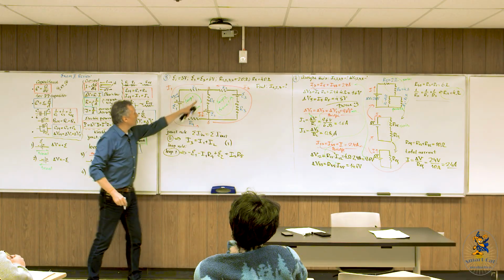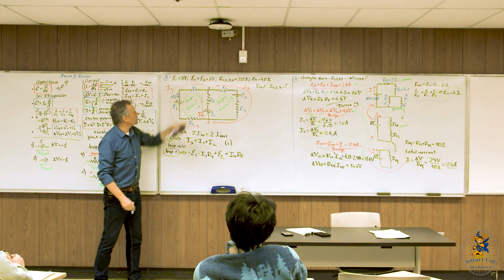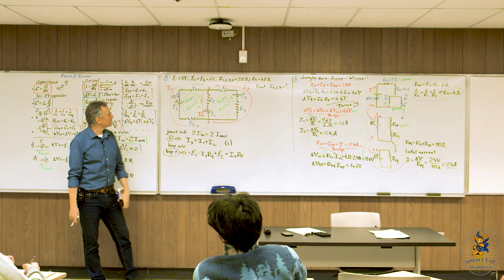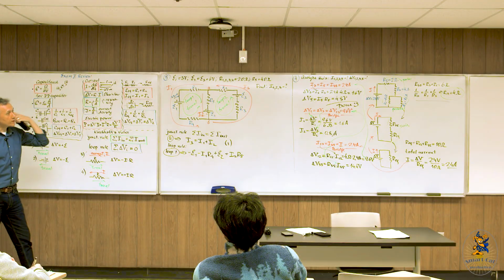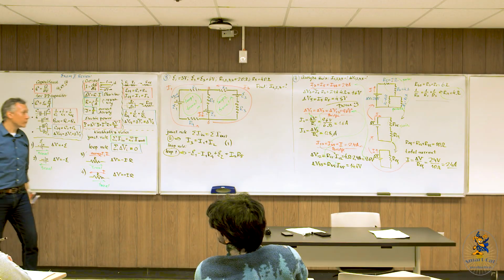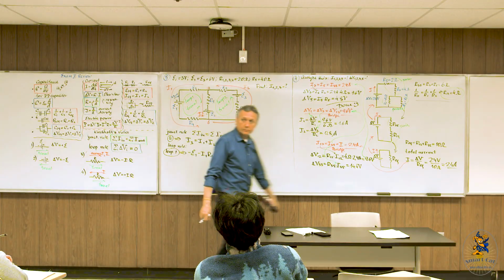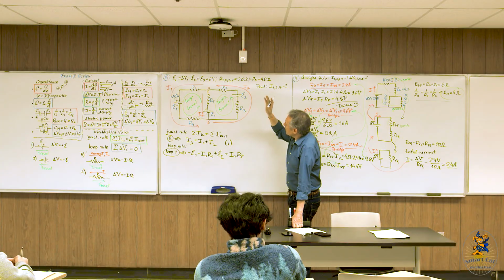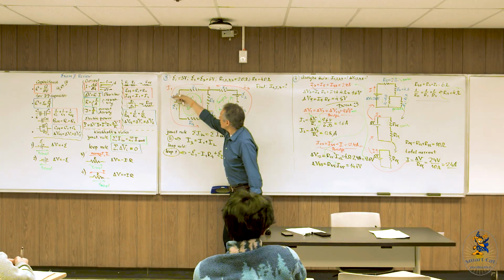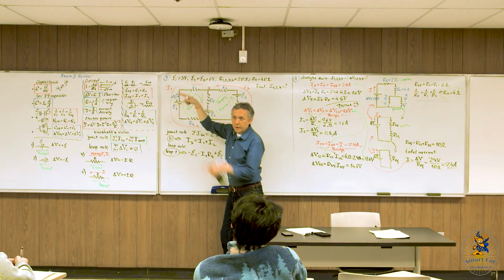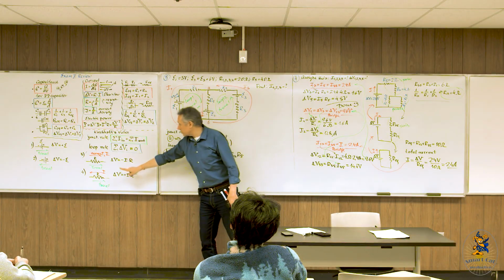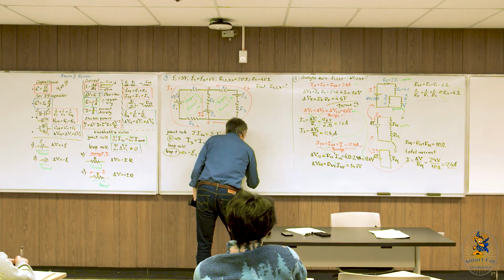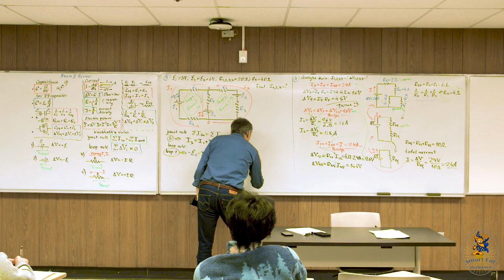Whew. So done with this small bridge. Now we need to cross this resistor R1. So what will be the contribution of resistor R1 when we move across it? Okay, good. You picked the correct current. So negative travel direction this way, current direction also the same way. So directions are the same. Contribution must be negative. Minus I1 R1. Yeah. Minus I1 and R1.